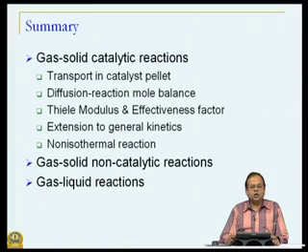For that we defined what we call the Thiele modulus, which rates the time scales for diffusion to the time scales for reaction. If diffusion time scales are very large compared to reaction time scales, the Thiele modulus has a large value, which implies that we are in a diffusion controlled regime.